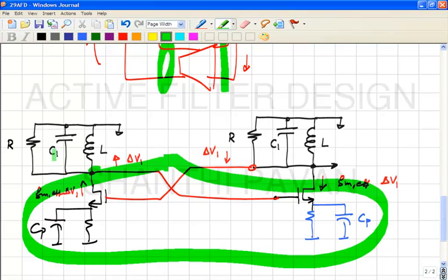So you have an RLC network which is lossy because of the R, but now in parallel with it you have a negative resistance. So if the net resistance is negative, what do you think will happen? The poles will be in the right half S plane and this will oscillate. But what kind of oscillations are these? What mode of signal is this? For common mode. Please note that this equivalent circuit is only for common mode signals.